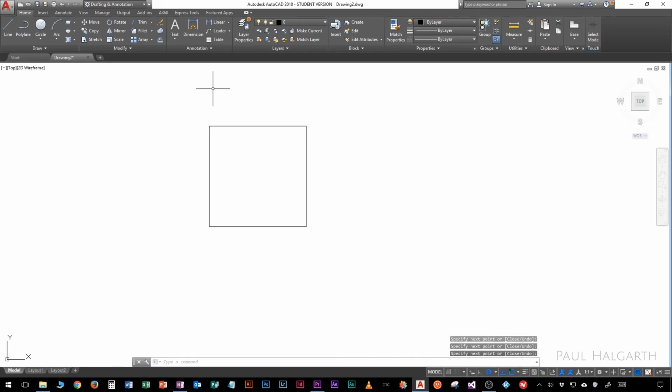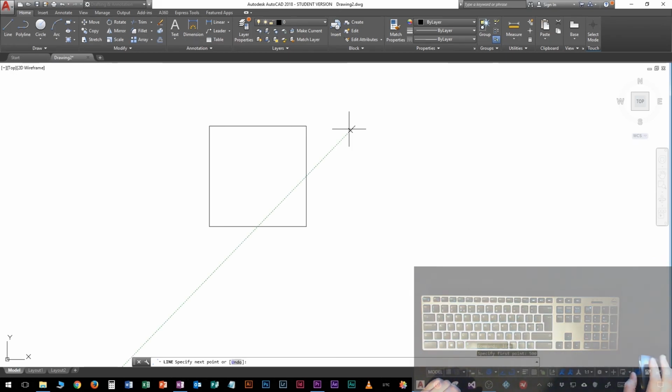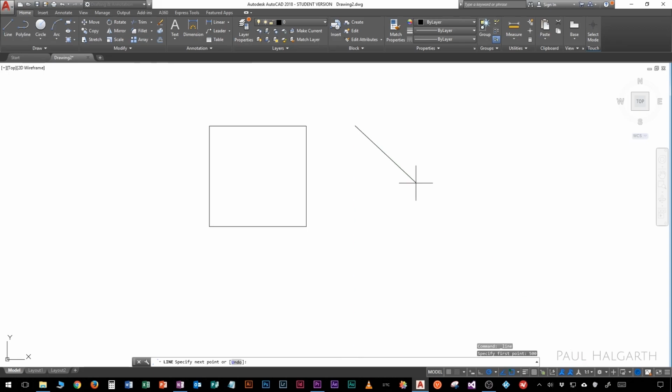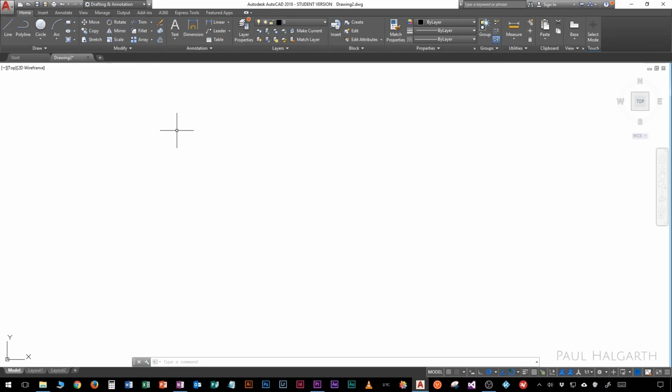Another useful feature of this is if I wanted to draw a line, let's say 500 millimeters away from this point, with object snap tracking on, I can just hover. I haven't clicked yet, just hover, let it pick up and put a green square, pull across, making sure again that I get this black cross through my cursor and a green dotted line, pull across any way that you want it to draw, type in the amount, 500, press enter, and it is now drawing a line 500 millimeters away from that point.